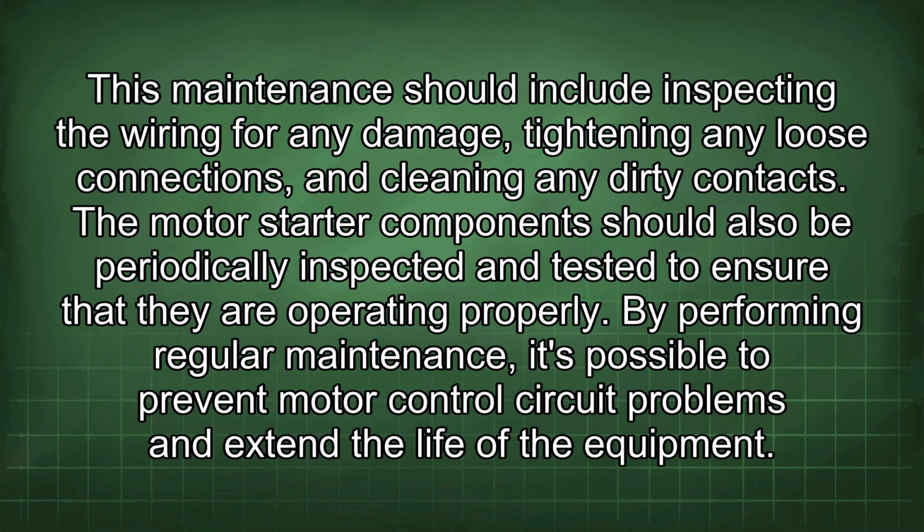This maintenance should include inspecting the wiring for any damage, tightening any loose connections, and cleaning any dirty contacts. The motor starter components should also be periodically inspected and tested to ensure that they are operating properly. By performing regular maintenance, it's possible to prevent motor control circuit problems and extend the life of the equipment.